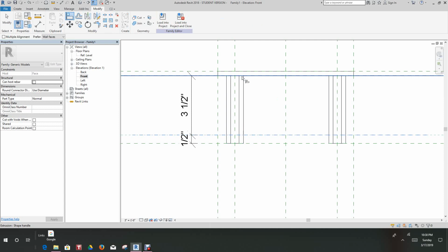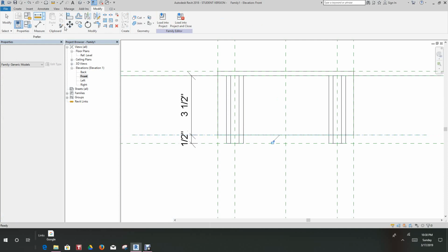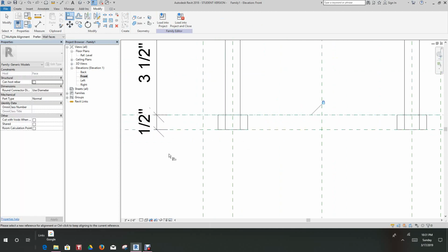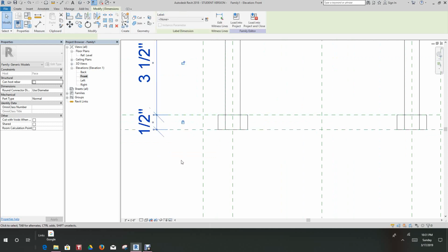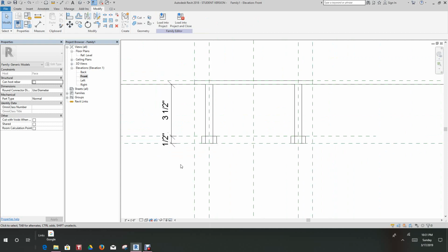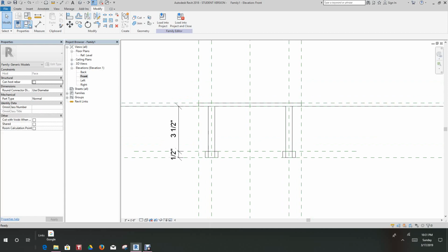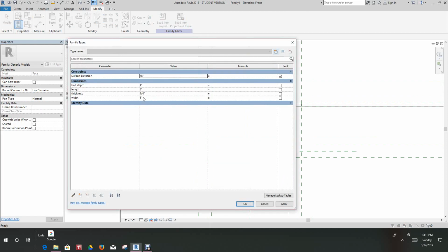to this line. We need a tab to make sure we pick up, oh, undo that, sorry. We want to tab, we want to align this again, we want to align it to here. So we want to tab till we find out when we got it locked in. Now we'll select this dimension right here and we'll lock it. Now let's test this and see if we can flex this properly. Hopefully we will. If not, we've got to do some more constraining.